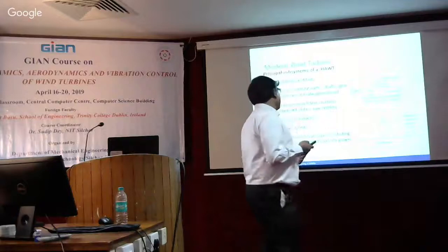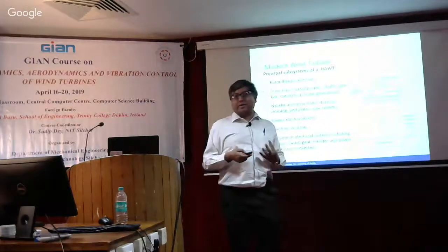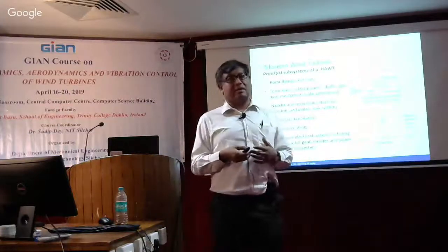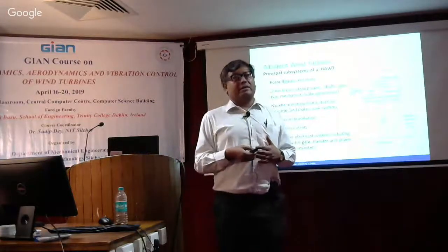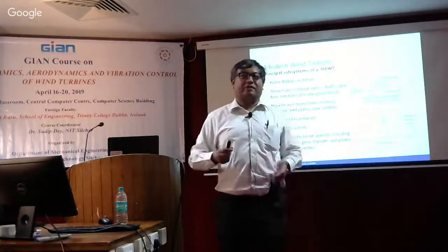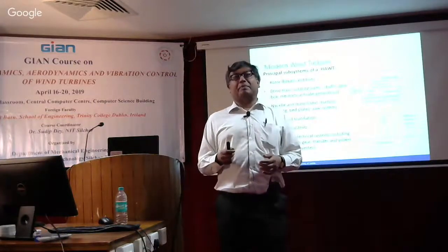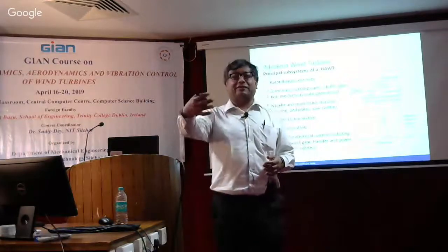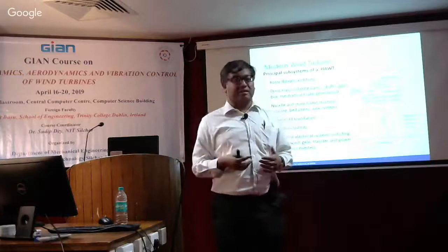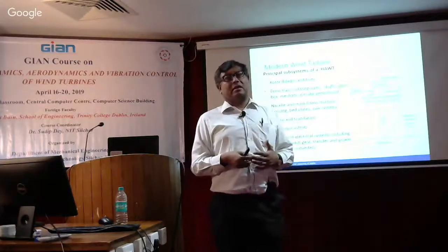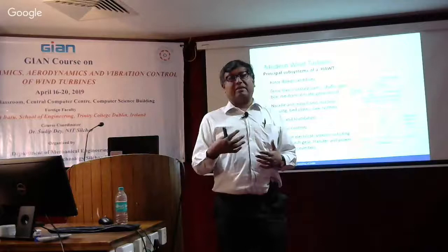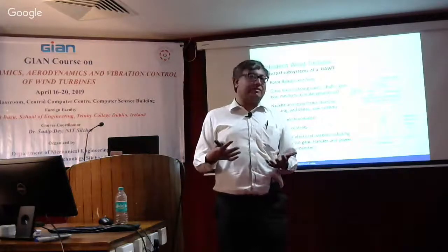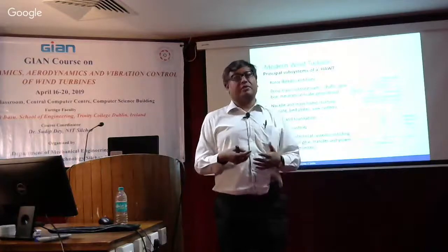So it's a very specialized job, and this is where a lot of people use deep learning and machine learning these days, trying to see this SHM or PHM, all this kind of thing, to see when the next gearbox replacement is needed. So predictive maintenance, proactive maintenance, and all those sort of things. So they acquire the data, they use either historical data to compare, benchmark, or they use different schemes to identify faults and conditions of the system.